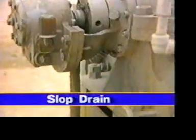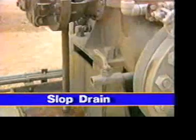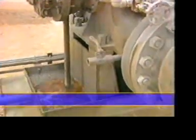The external section of the lower casing half may form a small open well to catch fluid leakage. There's a pipe called a slop drain at the bottom of this well. Leakage can be drained through this pipe. Now let's take a look at the stuffing box. It holds the packing gland. That gland, in turn, is designed to regulate fluid leakage around the shaft. We'll talk more about pump packing in the next section.